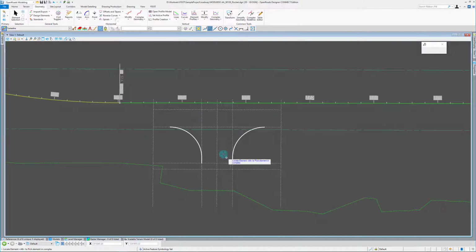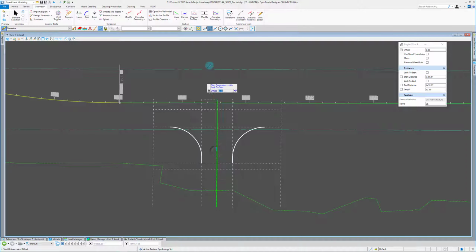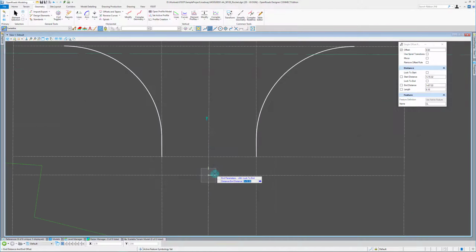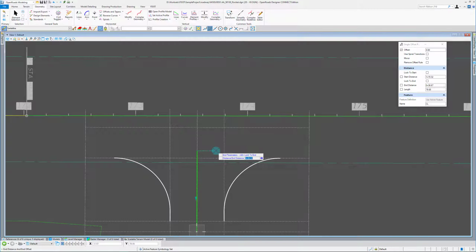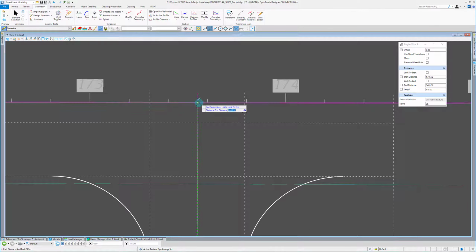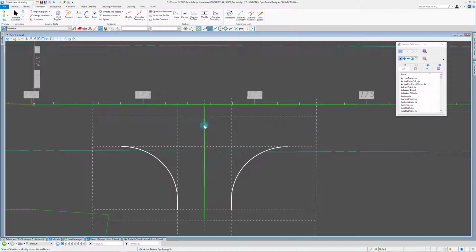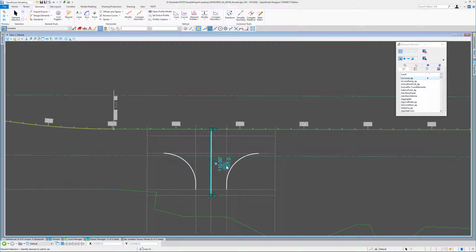I'm going to do a single offset partial following that south to north. I'm going to snap to here, so that I'm a little bit beyond my limits. When I look at this profile, I can see the existing ground a little bit beyond where I'm tying down, to get an idea of what kind of slopes I'm looking at coming in, or starting the profile. Then we'll snap that to the center line where it's going to end. That gives me a nice even number, 110.